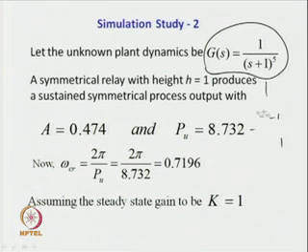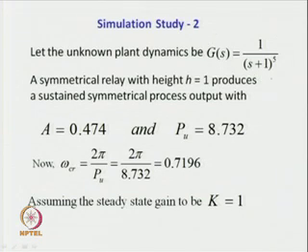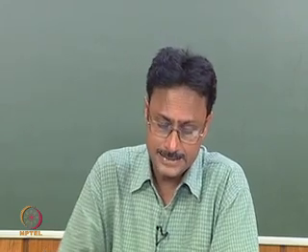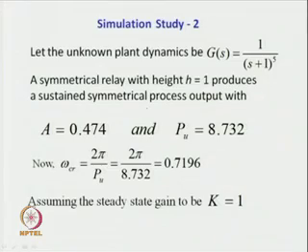So, it is possible to capture the dynamics of actual plants by some transfer function models. Not necessarily one has to assume the form of the transfer function as same as the plant dynamics. In that case, a symmetrical relay with amplitude h equal to 1 produces a sustained symmetrical process output, and making measurement of the limit cycle output signal, we obtain the peak amplitude